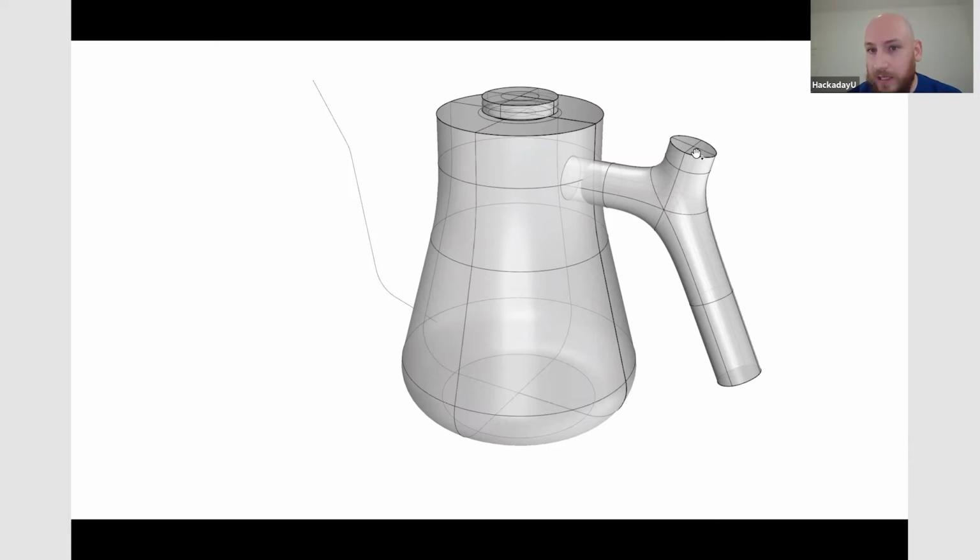I want it not to be capped, because a capped multi-pipe will make it smooth. So I have to do the caps manually in NURBS. See how it oversteps the interior of this revolved shape. I do the same thing here. I can just do a regular pipe there. Because these are separate curves, if they are not joined, these intersections won't work out properly. So it's very important that the initial curve is joined.